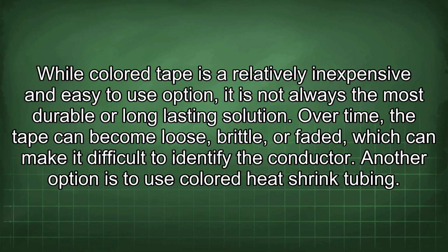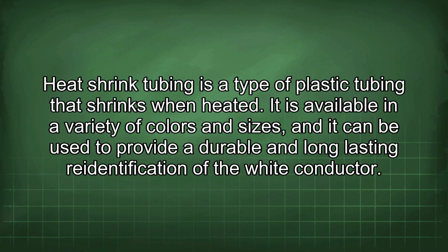Another option is to use colored heat shrink tubing. Heat shrink tubing is a type of plastic tubing that shrinks when heated. It is available in a variety of colors and sizes, and it can be used to provide a durable and long-lasting re-identification of the white conductor.